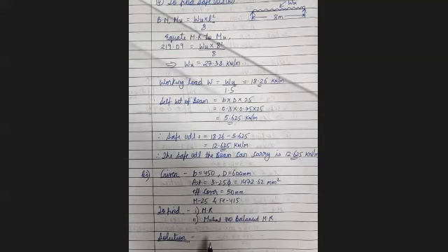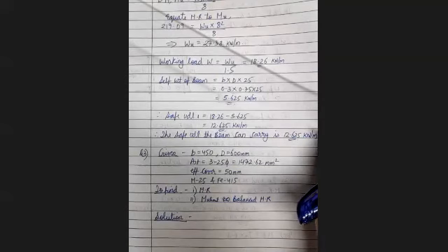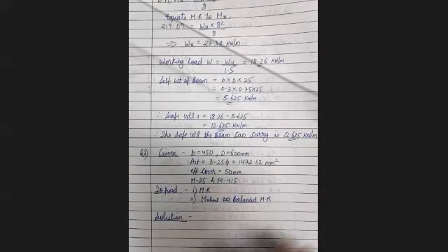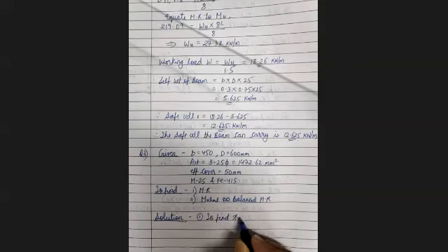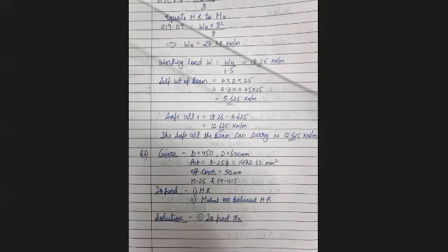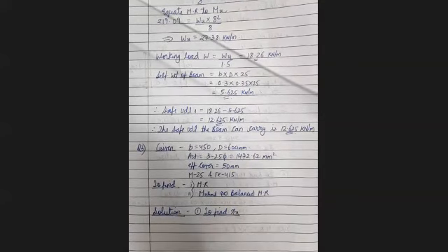So now, give me the value of MR, then we'll find out balanced MR. ठीक है, सबसे पहले we'll find out XU. So give me the value of XU now. You have to be a bit quick now, since we have already solved so many problems. So CU we will find out by equating CU equal to T. 131.28. Okay, fine. So XU we are getting as 131.28 mm.